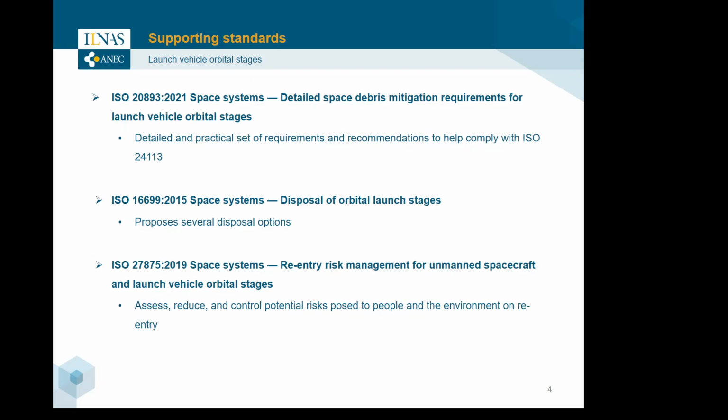ISO 20893 gives a detailed and practical set of requirements and recommendations to help comply with ISO 24113 regarding avoiding the release of space debris, disposing of a launch vehicle orbital stage after the end of its mission so as to avoid a breakup in orbit and so as to minimize interference with the protected regions, and safely re-entering a launch vehicle orbital stage. ISO 16699 addresses the disposal of these orbital launch stages.